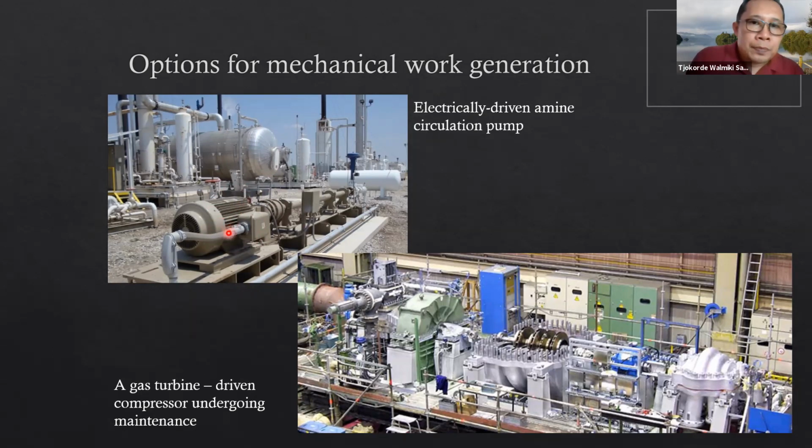pump stops. So more often than not, people install more than one pump when it comes to amine circulation. So if one pump runs into trouble, the other pump can act as a backup. Sometimes they even install 3 amine pumps. Believe it or not, in large plants they install 3 amine pumps. So usually 2 are working and 1 is on standby.